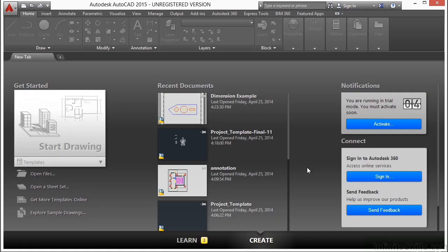Making a design in AutoCAD is more than just drawing lines and circles. It's a complex process that's been developed so that we can create complex designs. One of the keys to efficient CAD work is to organize your data in a way that you and others can retrieve it and understand it. Model Space is meant to be a three-dimensional area where you can draw and create your design. Your design needs may not include three-dimensional models, but only two-dimensional, and that's okay. Regardless of how many dimensions your design requires, the model for it belongs in Model Space. Let's look at some examples.